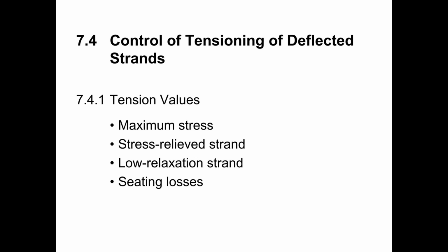The key requirement that is relevant to the plant is that 80% limit as the maximum force that can be applied to the strand at any given time. And that's in that second paragraph on page 711, referencing that 80% limit.